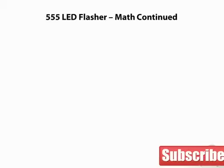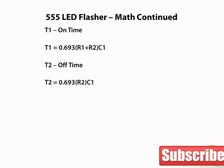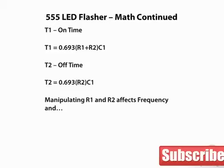For those who are interested, T1, or the on time, is given by the equation T1 is equal to 0.693 times (R1 plus R2) times C1. And the off time, T2, is given by the equation T2 is equal to 0.693 times R2 times C1 for astable operation. We can see by manipulating the values of R1 and R2, we can adjust not only the frequency of the oscillator, but also the duty cycle. Try it out and see if you can think of some neat applications for this versatile circuit.